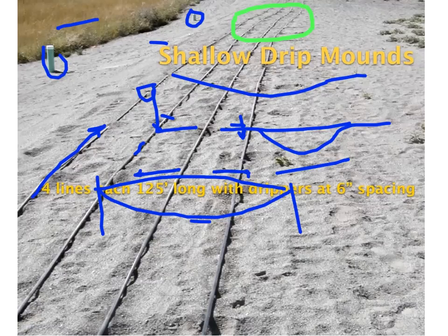If this is too high, if you have something like that, then you might have to run another line across here and then put an air vacuum relief valve connecting them at the top, so that when you switch off, again you handle the vacuum set up as the lines drain that way and that way. So you connect all the laterals with another manifold and put an air vacuum relief valve at the top again.